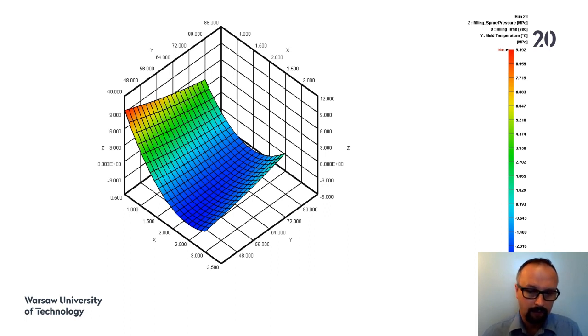But in terms of mold temperature, we see almost a dominant role of the injection time, so of the injection rate, and that still this optimal value determines the lowest sprue pressure. And it also seems that the lower the mold temperature, this sprue pressure goes down too.